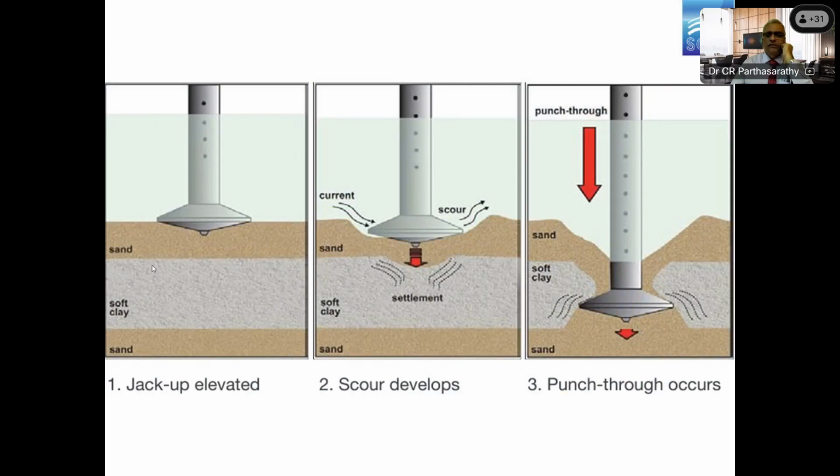You see, the sand is also stronger than the soft clays, so this can happen, or if this is treated as a crust layer, it could also penetrate because there is a settlement of the soft clay layers, and suddenly the rig will start penetrating below those layers, and passing through that, it could stabilize somewhere in a competent material where your shear strength can increase, or you have a high bearing capacity material.